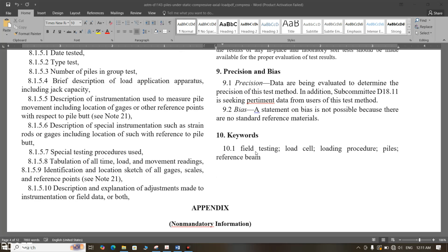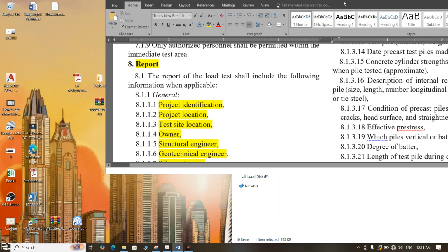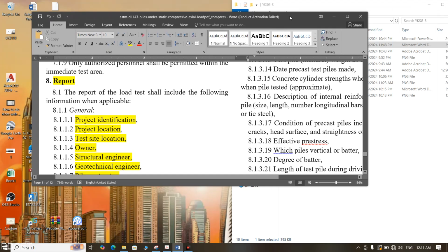We may now discuss the procedure of the test pile test. At first, construct, and then the pile is driven into the ground. Third, the pile top is prepared as a smooth level. Then a hydraulic jack is set up on the pile head. A primary steel beam is set up above the jack and a secondary beam above the primary beam.